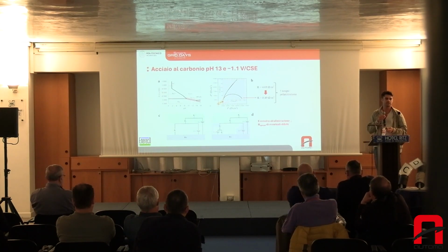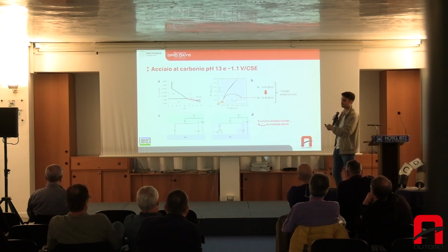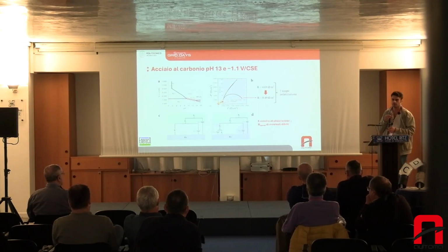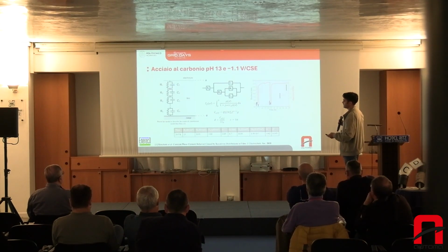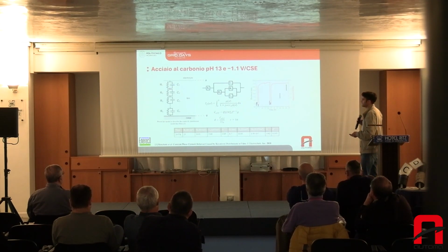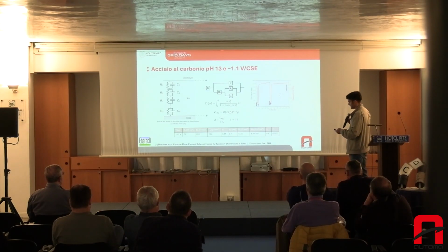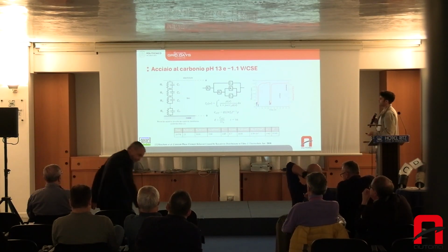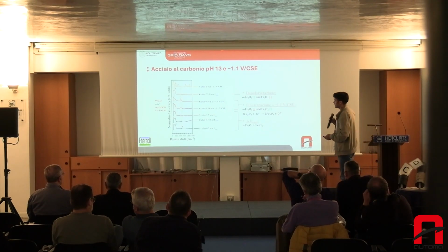Therefore, it would be interesting to assess if there are high densities of alternate current. It would be interesting to analyze the upper limit to use for the continuous protection current so as not to have any corrosion. Through the electrochemical analysis, it is possible to have the values of thickness of these oxides, normally some tens of nanometers, and their thickness increases as time goes by.